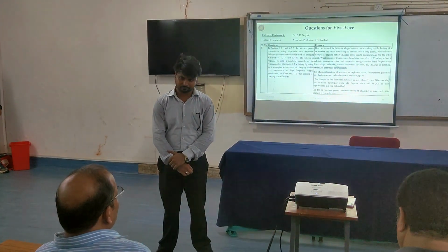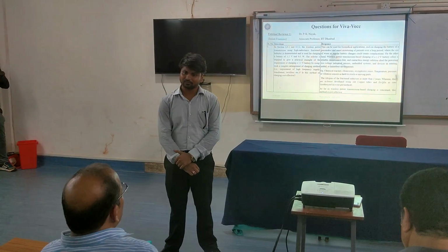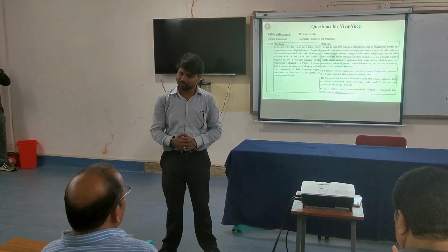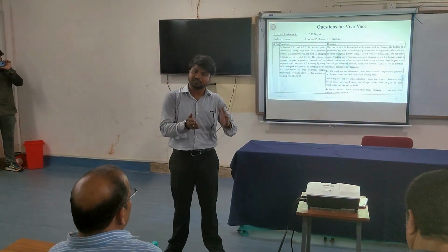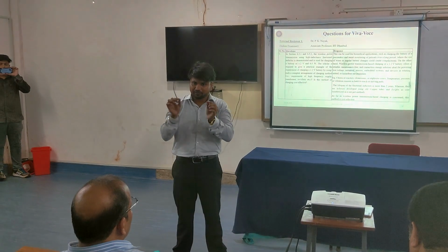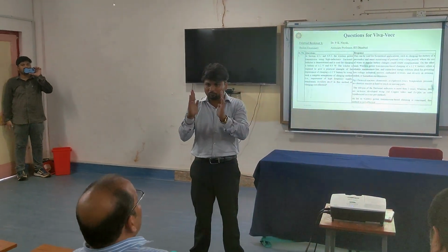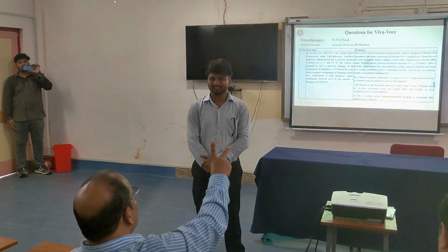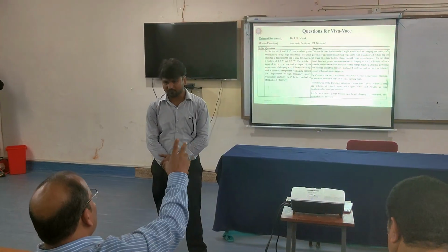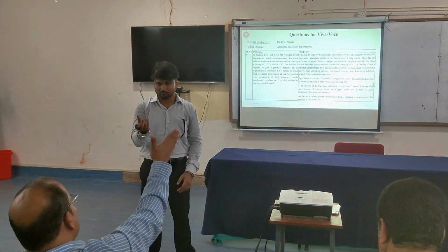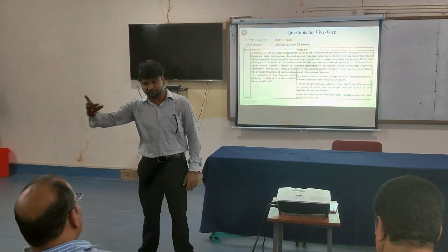And how do you measure it? Sir, we obtain the frequency domain analysis, and from the frequency analysis, the phase at 2 decades. That phase difference will tell you the fractional order: the phase, alpha minus 90 degrees for a capacitor, divided by 90, gives the order.